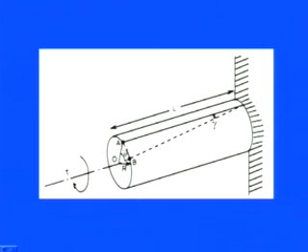Earlier this point was A, and now from A to B these layers have shifted from this point to this point. So we are measuring in terms of angle of twist. If this point O is the origin from where the central axis of the shaft passes, then this is my radius capital R, and this is my angle of twist, theta, from A to B. So this is the arc. And if I want to measure the distortion, it is the shear strain, which is equal to gamma.